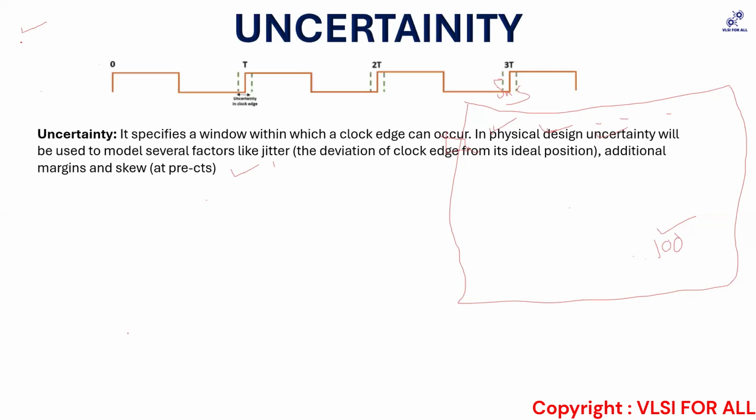Now, because of this uncertainty, the way the clock arrives can be a bit early or a bit late. Okay. And whenever you're doing timing analysis, whether it's setup analysis or hold analysis, you're always taking the worst possible case delay.